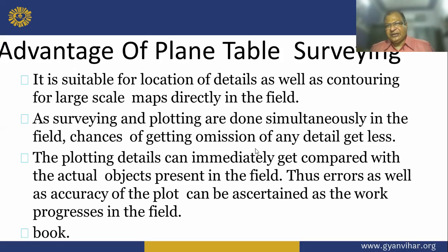So, advantages of plane table surveying. It is suitable for location of detail as well as contouring for large scale maps directly in the field. Surveying and plotting are done simultaneously in the field. The chance of omission of any detail is less.